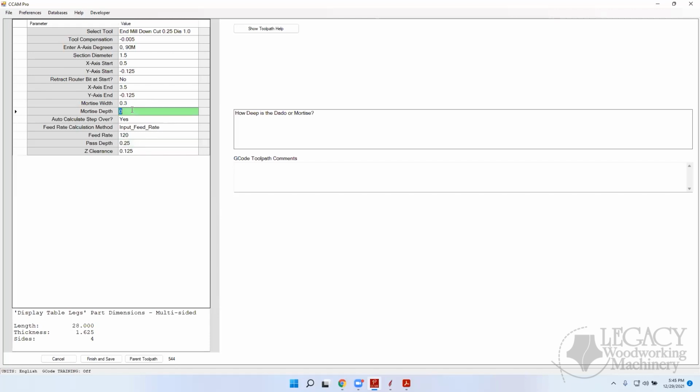All right. So let me see, the mortise depth, we got the width. Now we're going to put the depth. I put this on the drawing, so we could go look at the drawing if you have any questions, but it's going to be 5/8 of an inch deep. The tenon is only going to be 0.6, so we're going to leave that 0.025 inches of gap for glue.